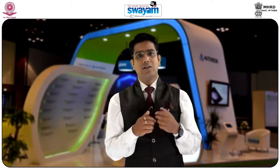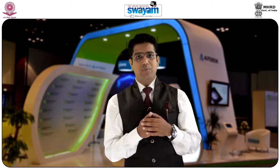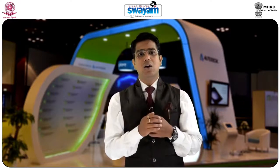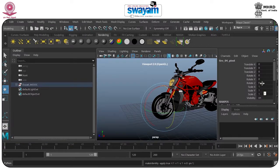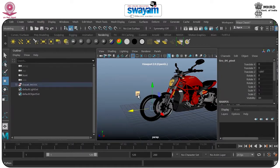Sometimes we want to reset all the settings in the channel box to 0 without changing our object's position, rotation, and scale. What you can do is go to Modify and hit Freeze Transformation to reset all the values, and here you can see in the channel box. Now your object may be moved to some new space, but after hitting Freeze Transformation, all the values would be 0, 0, 0. So now it's a local coordinate system, or the base coordinate system, of that particular object.